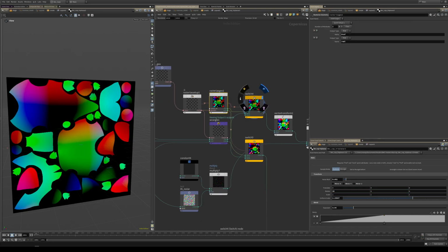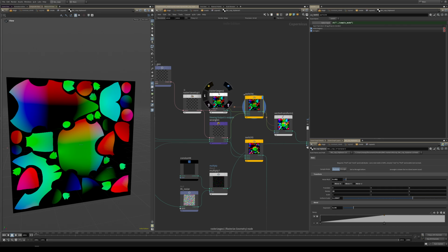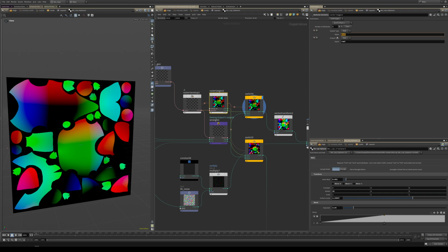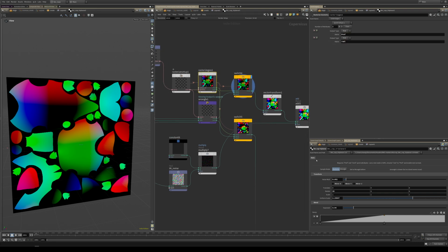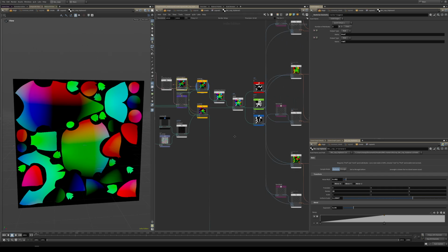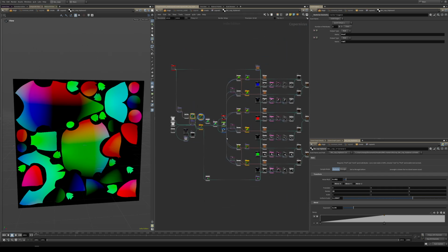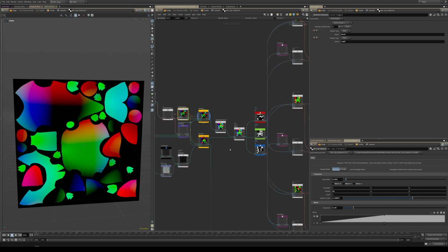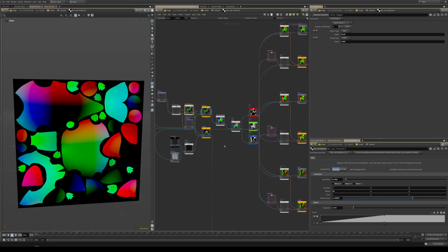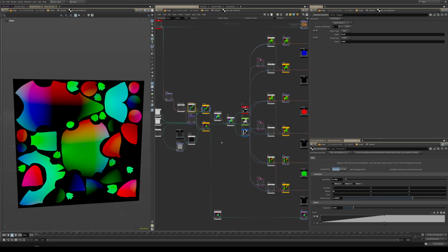So let's go to this switch. We have this Rasterize method, which takes the pref and the normal attributes. You can see it gets rasterized only up until the UVs. After that, we get black. This might cause some issues further down the line when you manipulate this information. At the end, you might see black or lines, artifacts around the UV island edges and seam lines.